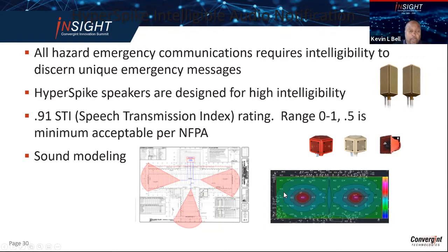So when we design for your facility's needs, we design it according to the environment. Having an omnidirectional speaker in a narrow enclosed environment is not good because it's going to echo off the wall. So we will use directional speakers. This is an example: a FedEx truck dock, and we have directional speakers because it's narrow.